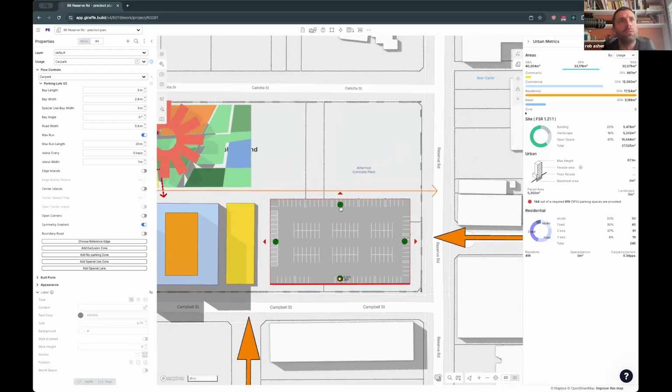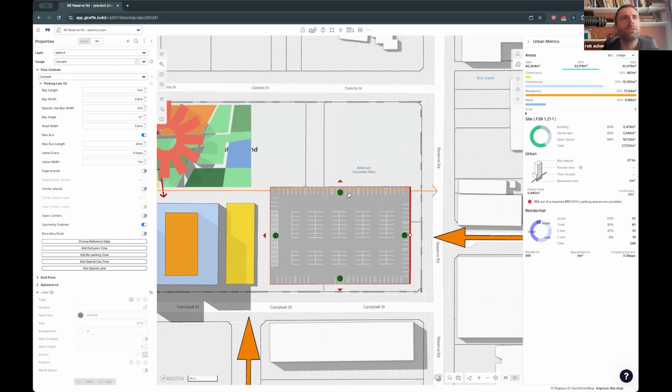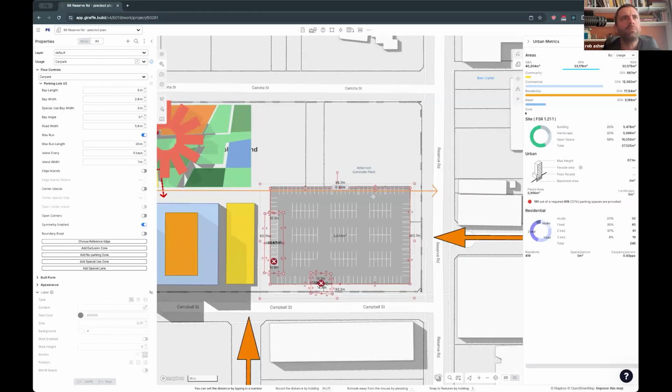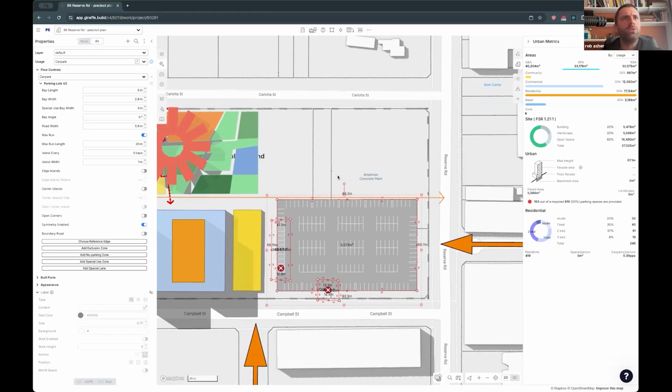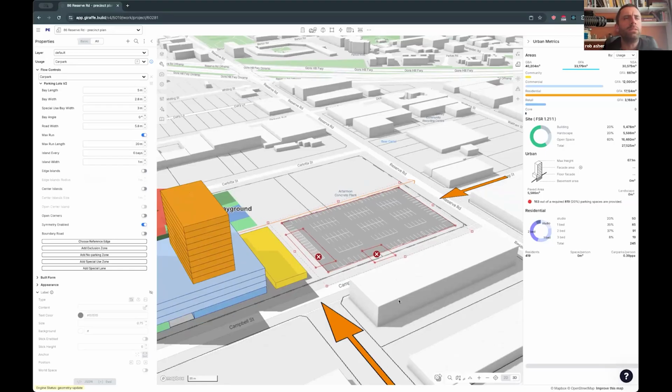So have a look at it, have a play with it. It's pretty fun. And you can see there, this max run is fighting with the shape and the geometry. So spending time tweaking the parameters is really interesting, and can get you quite different results. All right, so that's the new car parking algorithm. So we're just doing some nice on-grade car parking here.